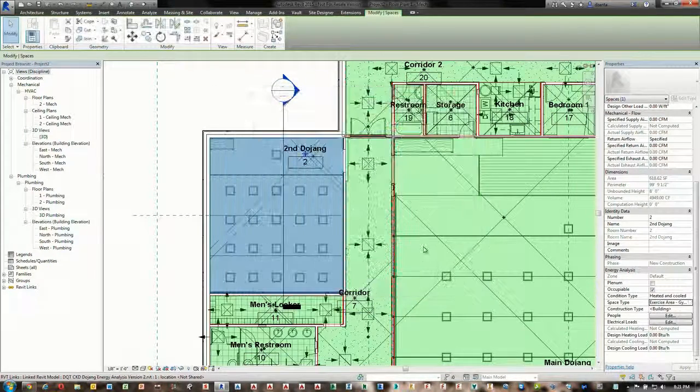This is the arduous part of doing this, because you may have hundreds of spaces in your Revit model. There's no way around it. You have to work with each space and select it and specify the BIM data. You had a question? There's a way to do it: you create a schedule. You just check itemize all instances, and so all your offices would go to one office type. So the solution, a faster way to work with all the spaces, naming them and setting their offset limits, is to create a schedule. Awesome. Makes sense.